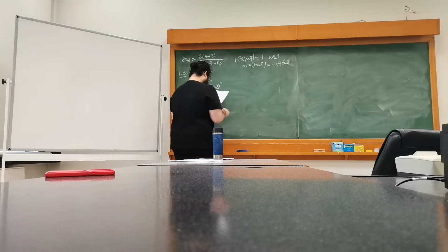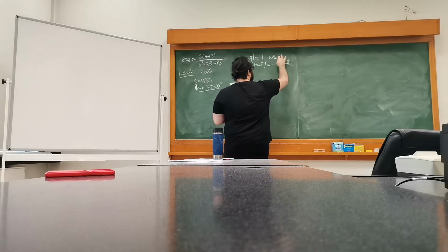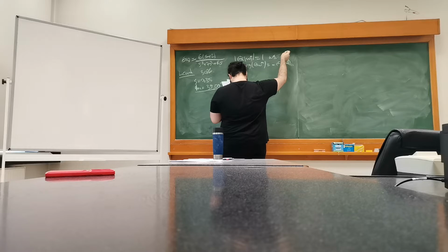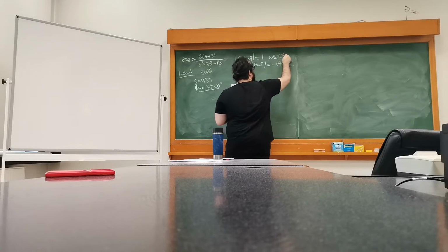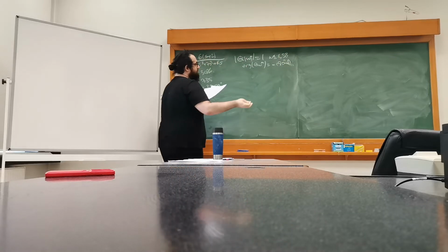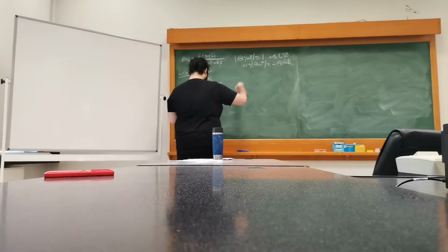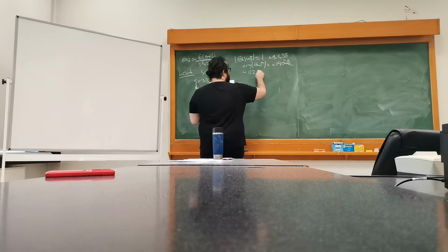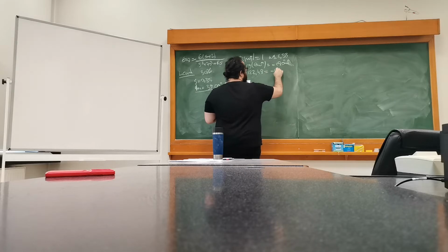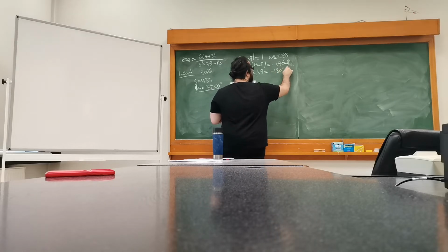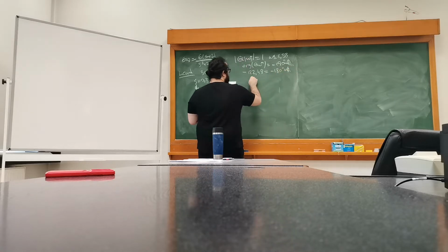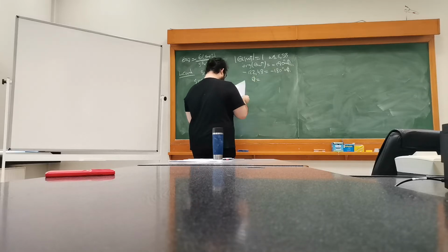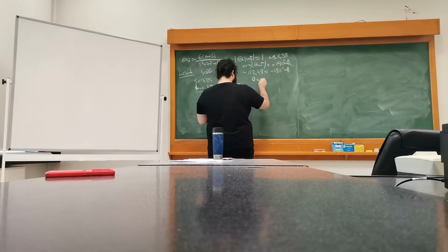That's going to be the phase margin of the system. Now, this happens at 1.38 radians per second. And if I plug that into the argument here, I'll see that this is minus 122.48. So I'm going to solve this as the phi value, and this phi value is equal to 57.51.